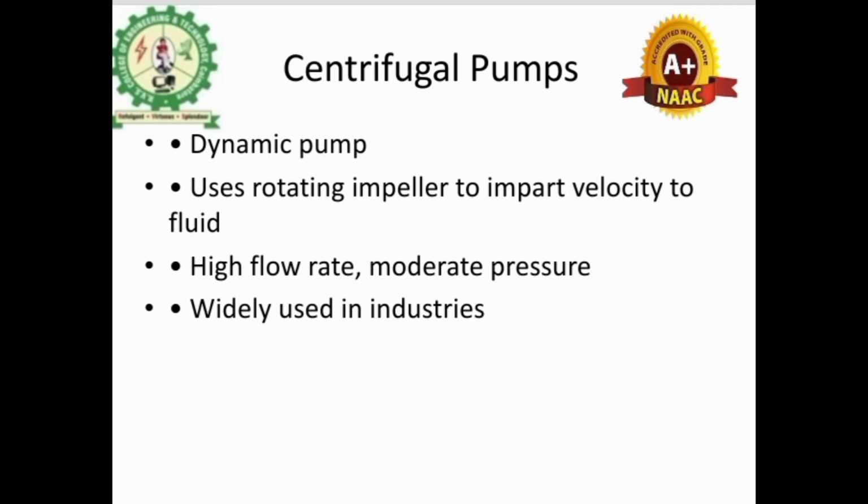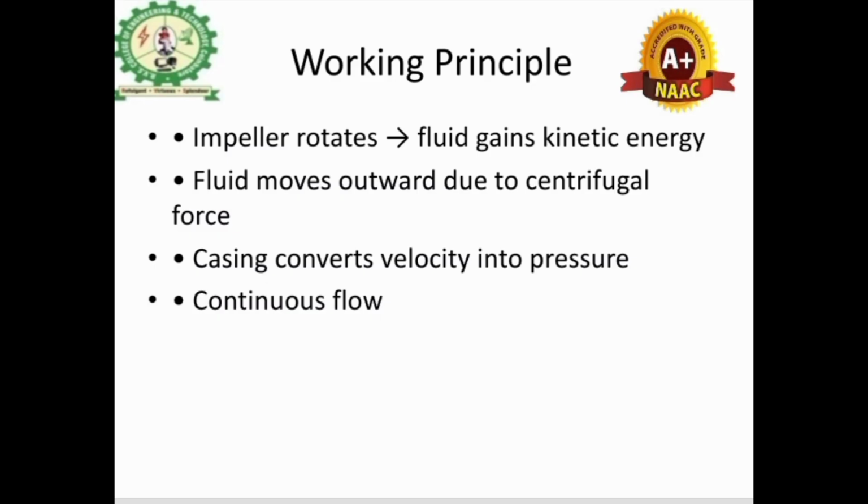When we consider the working principle of a centrifugal pump, they work on the basic principle of centrifugal force. The centrifugal pump has an impeller, and that impeller is rotated when power is given to it through an electric motor, and due to the rotation of the impeller, the fluid gains kinetic energy and the fluid moves outward due to centrifugal force. That is why these kinds of pumps are termed centrifugal pumps.